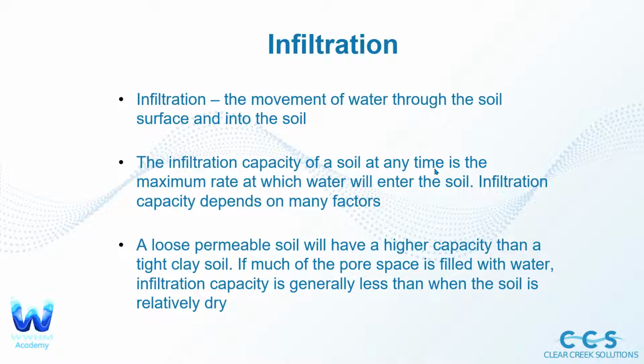But if you think about some sand, have you ever done sieve analysis? The particles are very, very small. There's going to be lots of gaps between them. When you think about something like clay, which is almost solid, and you dump a bucket of water on a patch of clay versus a bucket of water on some sand, the water is going to really infiltrate into that sand, but not as much through the clay because the particles are closer together. It's going to rely on the pore space to determine how much water is able to infiltrate through that soil.